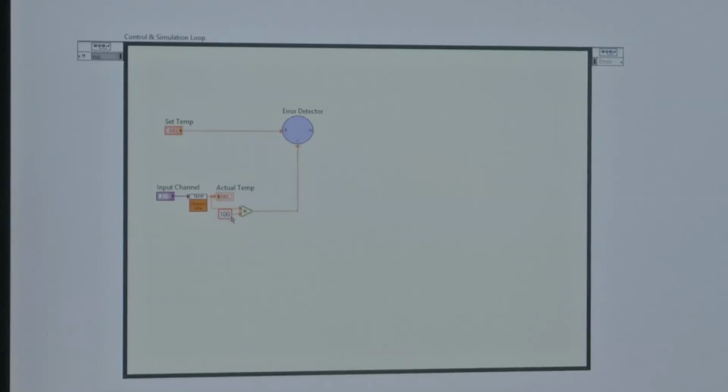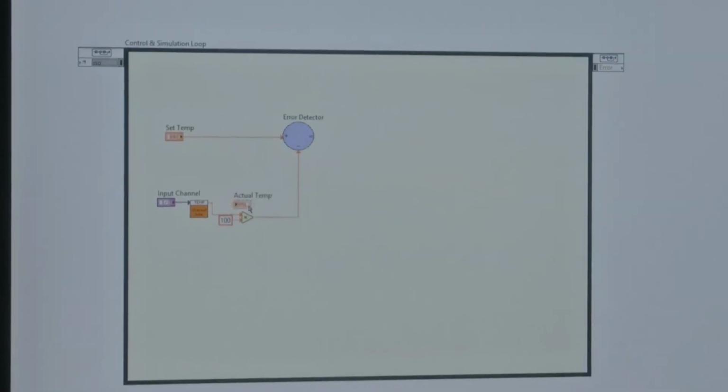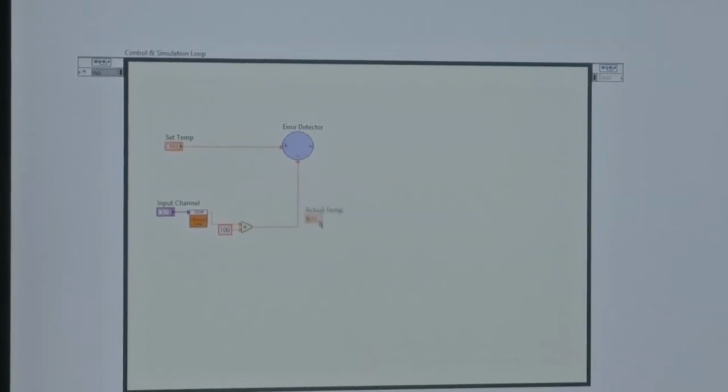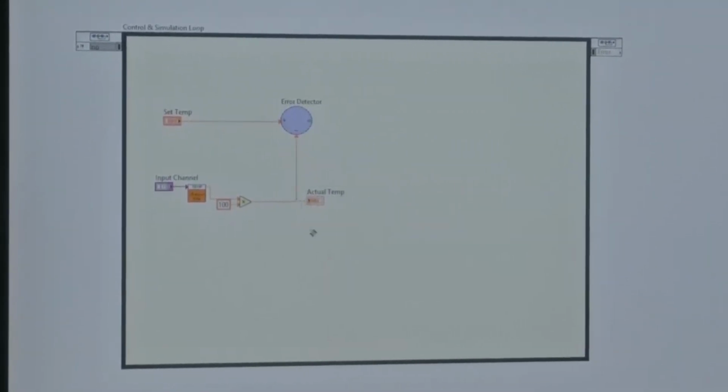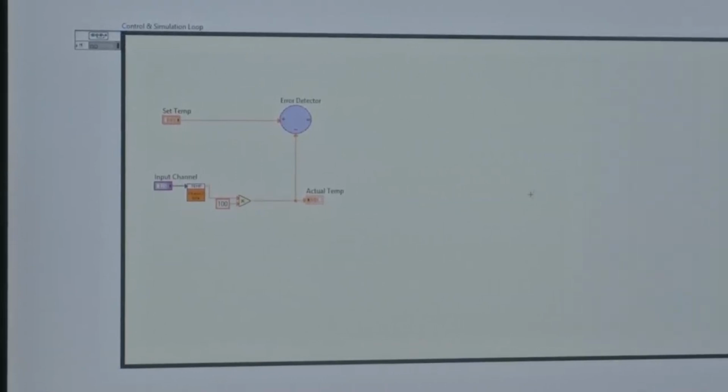So, 10 millivolt into 100, which is nothing but 0.1 volt per degree centigrade, even this 0.1 degree centigrade, right. Since it is easy to understand signals which have the same unit, the actual temperature I will be connecting it here. So, both are in the same unit, easy to realize. Now, after doing this, we get the error signal.